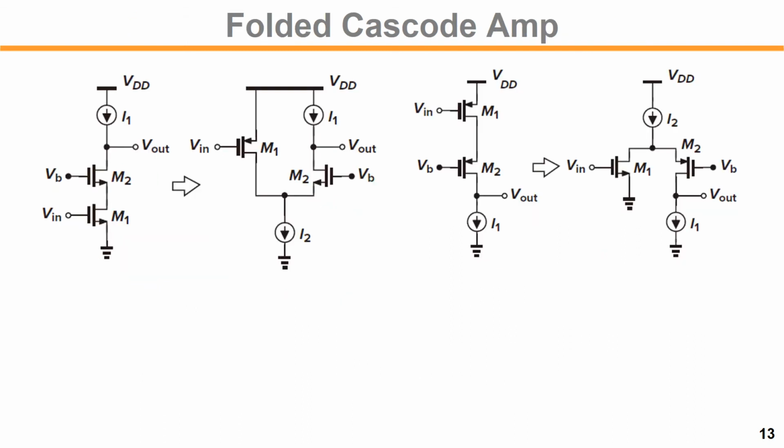So far we had looked at the cascode amplifiers, and we understood that any time you stack up the devices, your input and output signal ranges become more and more limited. So for this input and output here, your signal range is limited, right?